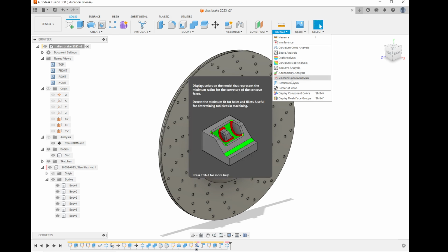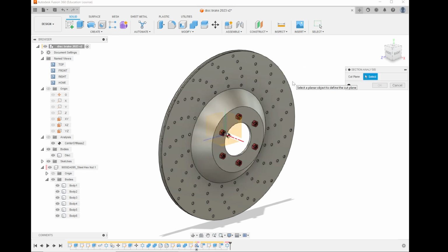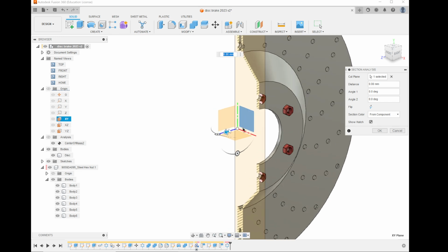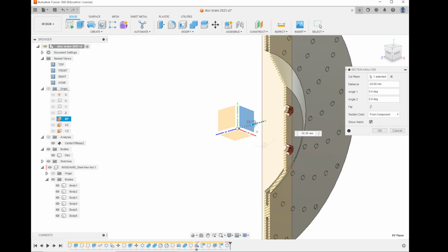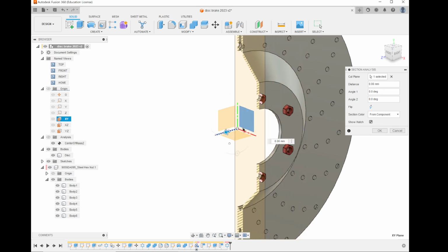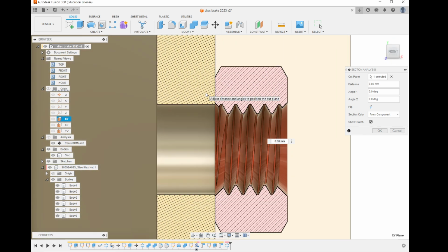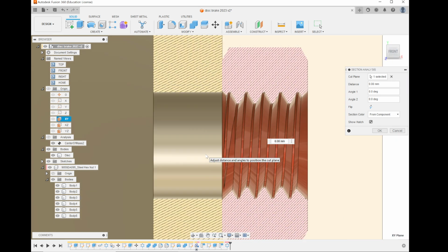Another thing we can do is inspect what the inside of a component looks like by doing a cross-section analysis. Press inspect cross-section, I press this plane over here, and if this all works, we can look visibly at what the inside of our object looks like. So this is like our drawings, and if we zoom in, this is actually what the cross-section of the drawings should look like. Remember how we said it had those angled lines and they change based on the material? So we can use that visibly.